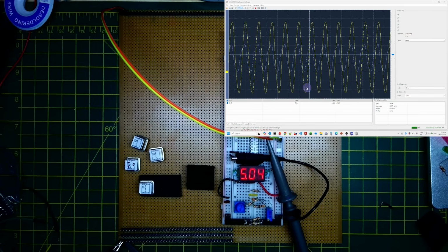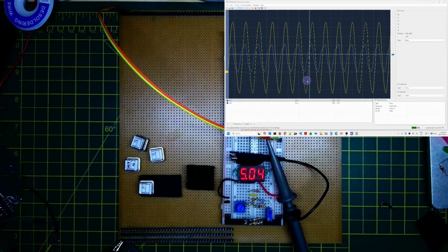So this is one of the problems with driving buses, in particular these sorts of parallel strips, and the inductance and things that you get from the various bits of wire. So I'm going to look into ways of mitigating and minimizing that. I think what this does indicate, though, is we probably don't want to put sort of 25 to 40 MHz signals over long bus rails and things. However, when we're down at the sort of 4 to 8 MHz, then it wasn't quite so bad. But that's just showing the output here for the buffer.